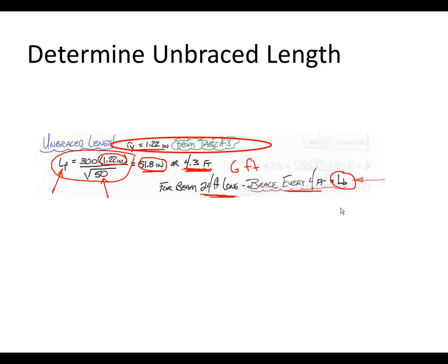You've gone through the problem. You started out by looking at bending and making sure bending was okay. And in the process of doing that, you actually selected a beam size. From there, you simply made sure the beam was compact. You checked the shear. You checked the deflection. And then we finally checked the unbraced length. Those are the 4 or 5 basic steps that go into beam design. I hope this will help re-explain just a little bit what the problem is all about. If there was anything in the problem, I'm hoping that this little explanation will help walk you through maybe where some of the numbers came from and what they mean.